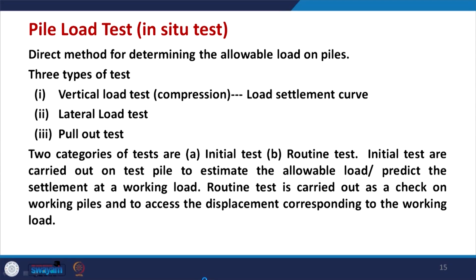Then the second is called the lateral load test, where you apply load laterally and then find out the capacity there. The last one is the pull out test, where you apply tensile load and try to pull the pile out and then test it.